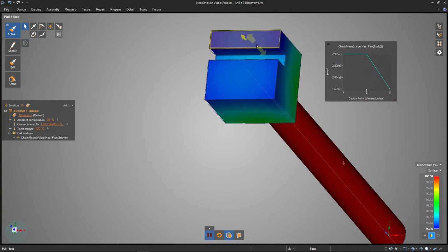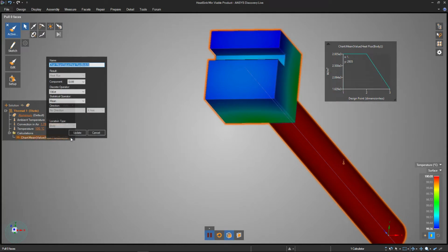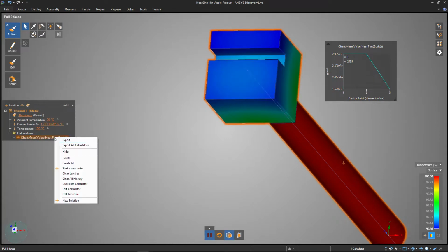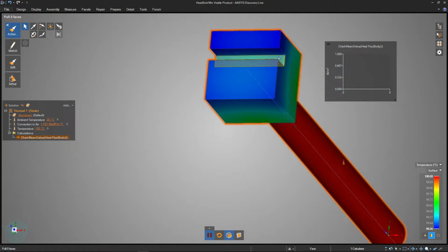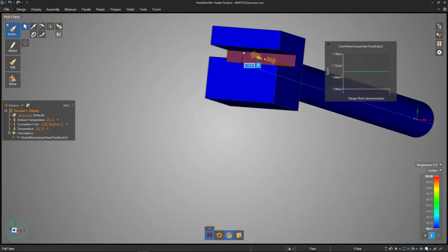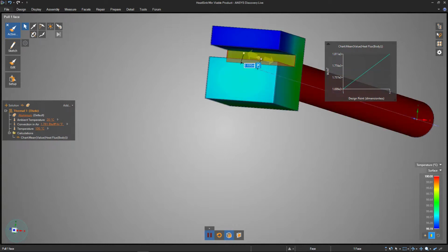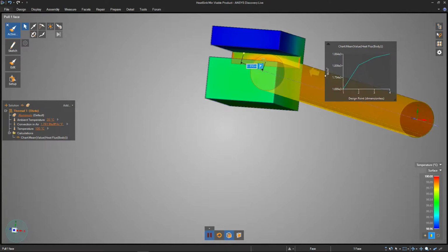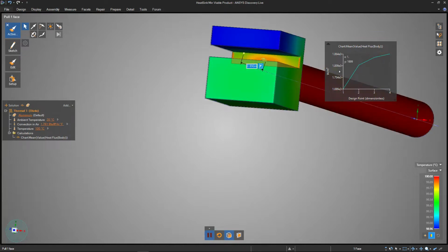Sometimes by defining that face on the surface, you actually see a decrease in the effectiveness. It doesn't hurt to right click on the calculator here to clear the information that was on there after adding that face. From here on out, we should intuitively see that as we increase the surface area, there is an increase in the heat transfer to the environment. So I've got 2 design changes there. The third one, making it even lower, is still going up, but starting to level off.